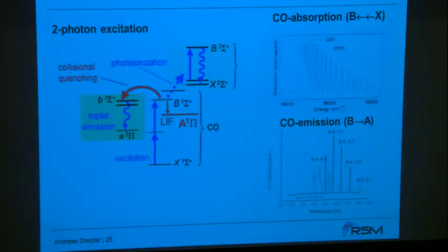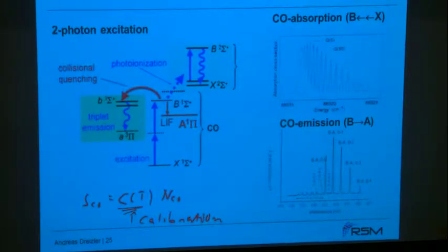That is the parameter that you have, as I mentioned as well, you always have to measure simultaneously, such that you have a calibration polynomial that is dependent on the temperature and links your CO signal with the number density of the CO. Yeah, and that is here from calibration. And that is then valid for a certain equivalence ratio when operating premixed.